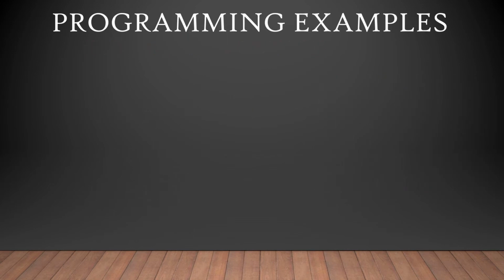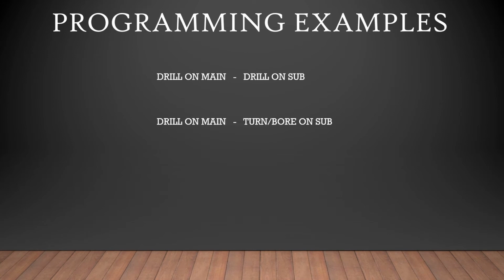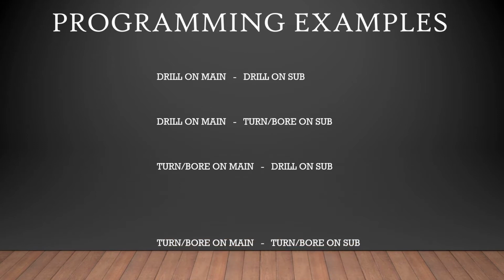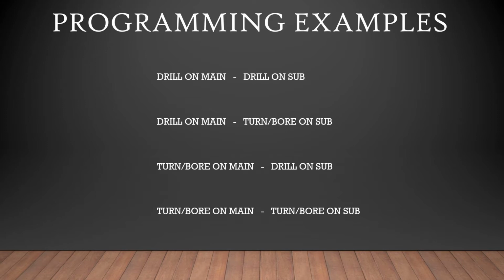Let's review again some programming examples. Drill on the main, drill on the sub, drill on the main, turn and bore on the sub, turn and bore on the main and drill on the sub, or turn, bore on the main and turn and bore on the sub. So these are just a few different configurations, popular configurations you can do with superimposition.